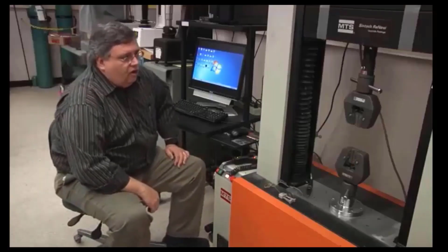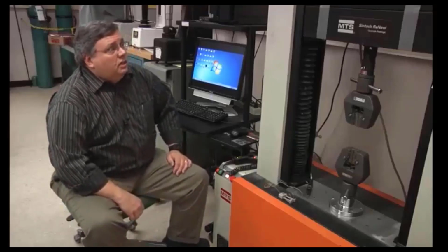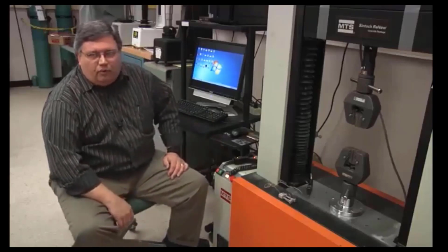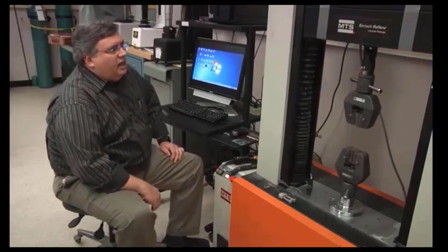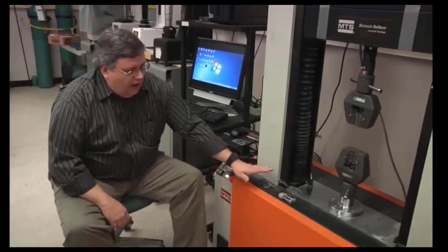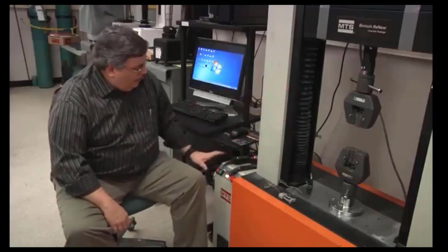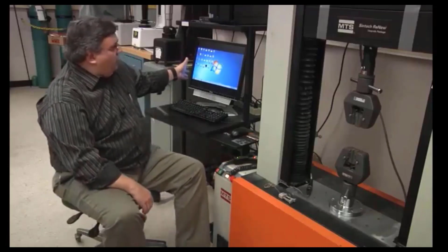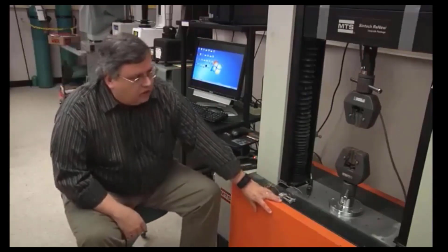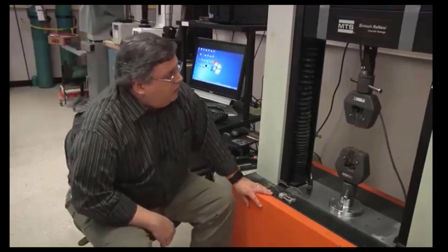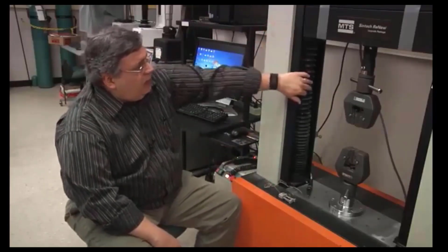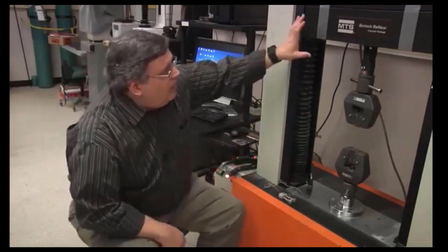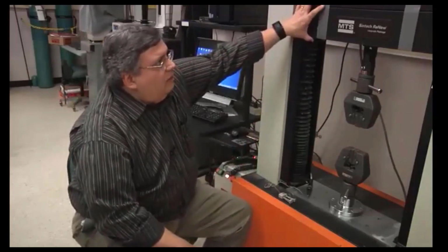This is our Instron universal testing machine. It's actually an old Model 1125 Instron frame, which was manually operated, and MTS has upgraded it. So we have our main load frame here, and then here we have our control unit, which interfaces with the PC. So the motors that drive everything are in the orange base here. The main components inside these pillars behind the accordion pleats, there are long lead screws that are turned by large stepper motors in the base. That drives the crosshead here up and down.